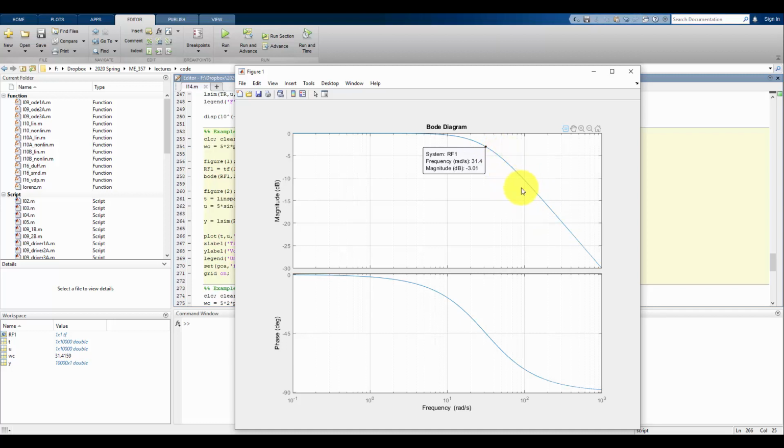But once we're sufficiently above the cutoff frequency, yes, those are going to have a very low magnitude. They're basically going to go away. And if we are sufficiently below the cutoff frequency, all of that signal is going to be more or less preserved. So we see here it basically drops to 0 by the time we're at about 6.5 radians per second.